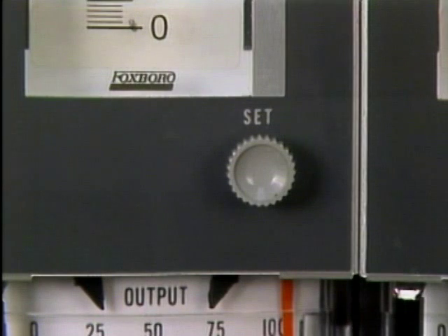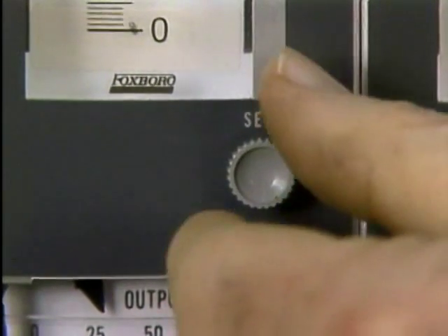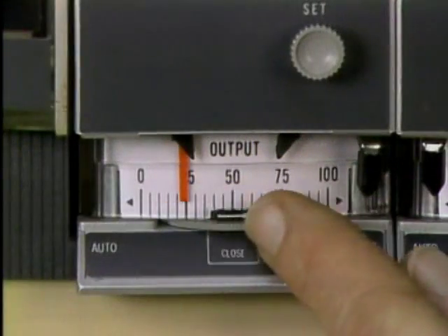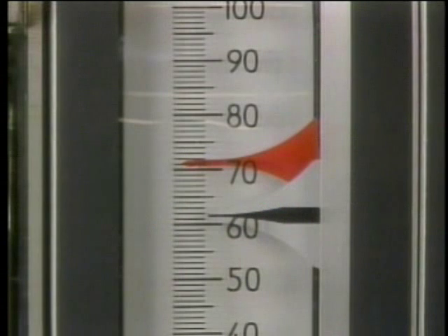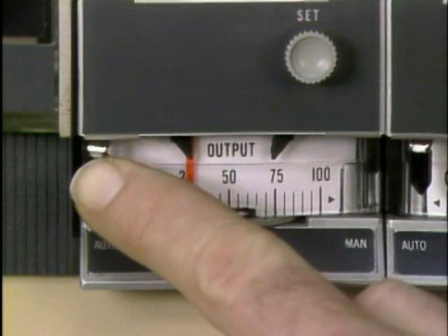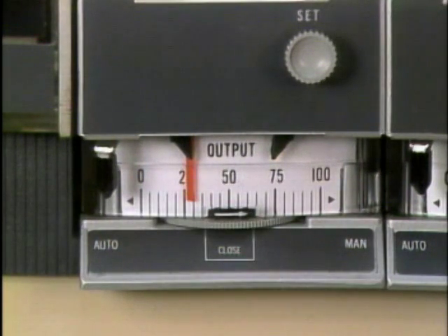In some cases, the value of set point is adjusted until it matches the value of the process variable. In other cases, the thumb wheel is used to adjust the position of the final control element until the value of the process variable is changed to match set point. Regardless of which method is used, once the two values match, the selector switch can be moved from one control mode to another without causing a bump.